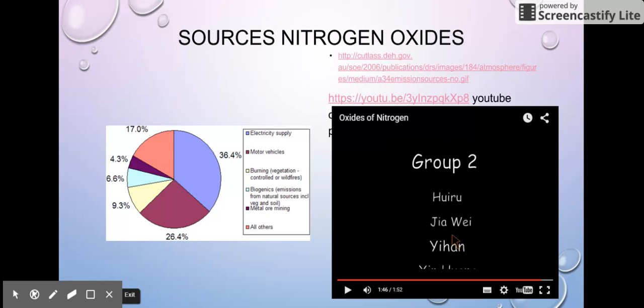So it's not actually that the nitrogen is inside the fuel, it's that you're creating almost like a mini lightning strike inside the air fuel mix. So if your timing is ever so slightly off, you're going to be reacting a lot more nitrogen oxides. And incidentally, they remove that using a variety of catalysts as well.